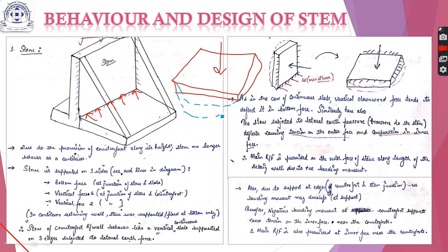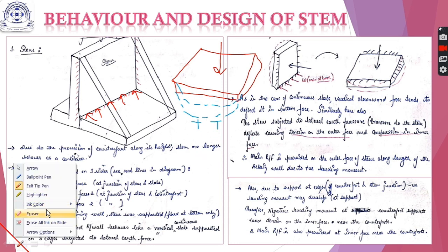As this is not a cantilever slab, it will deflect like this. If it had been cantilever, the deflection would have been reversed. So if this is type of deflection, so where is the positive moment coming, or where is the sagging coming? That is in the bottom face. So therefore positive bending moment or tension is acting on the bottom face of your slab, and compression is on the upper face. Okay, so is it clear to you? Now let us recall another case.